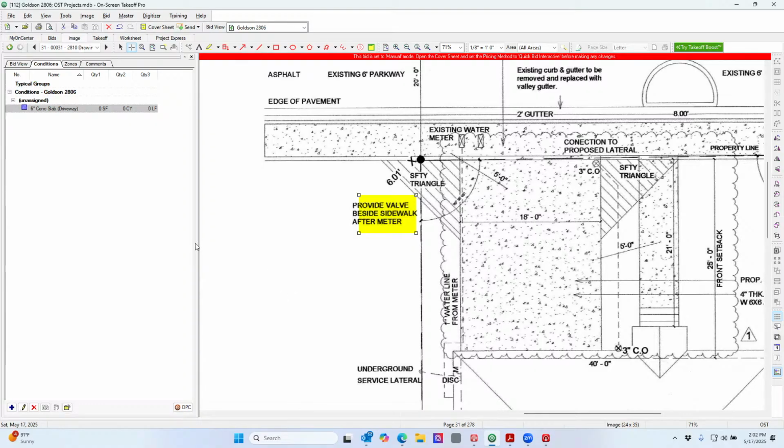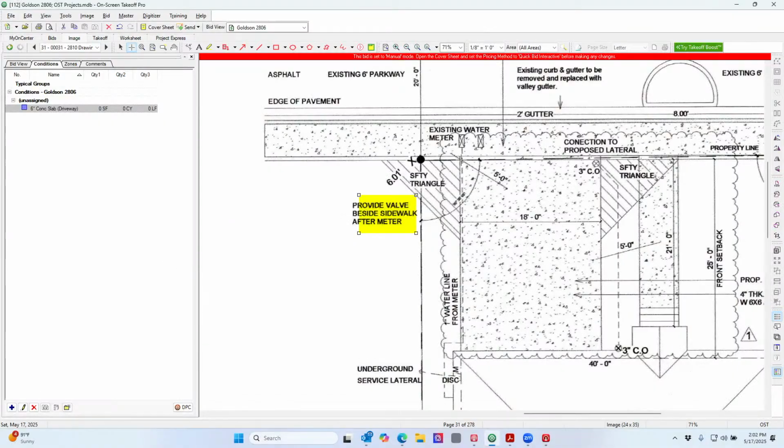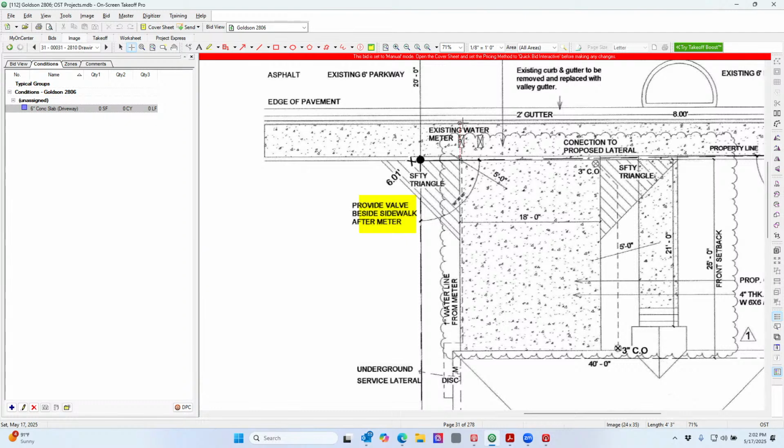So those are the... What would you do for a contingency? You would do a different takeoff for that? No, I would just probably put a number on it. You could do a takeoff and say, let's say for instance we figure we're going to have subs driving in and out. Maybe I do go ahead and take this off and say, in case we have to repair this, how much square footage would it possibly be? And so it's about 74 square feet, a yard of concrete. Okay. So then I would just price that and maybe use it as a contingency number. So you can do it that way as well. Me, I may say I may need like $500 or $1,000 just in case something happens here.